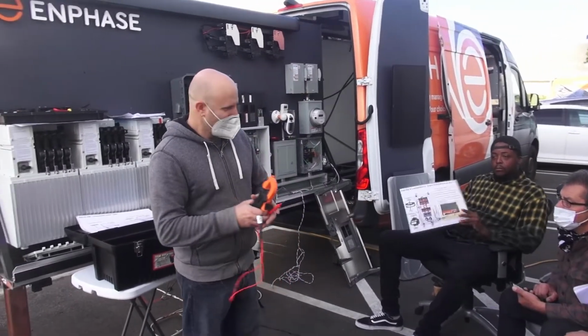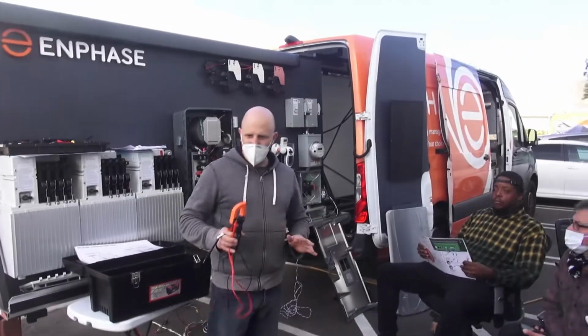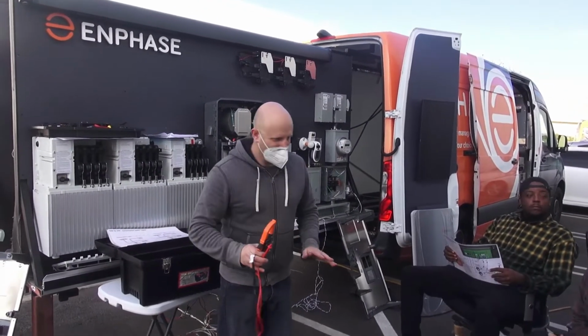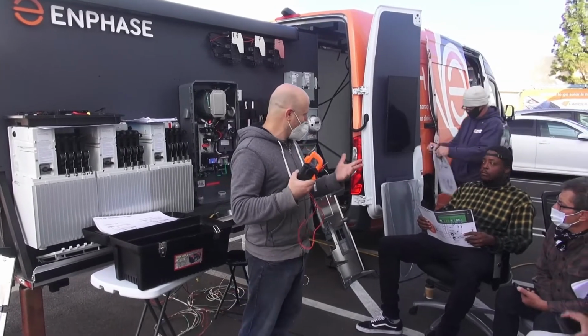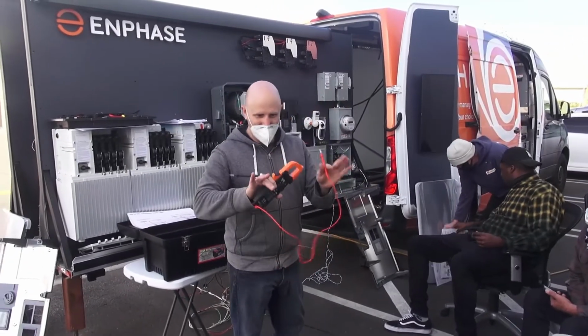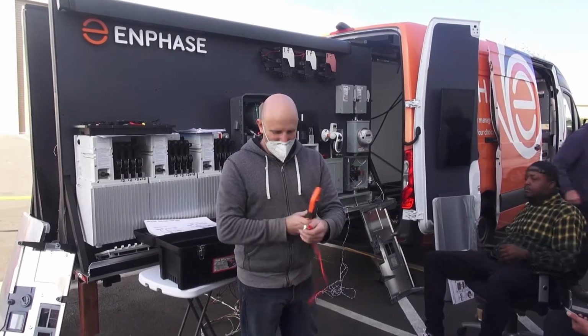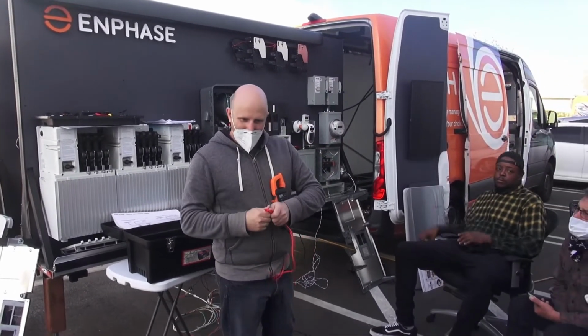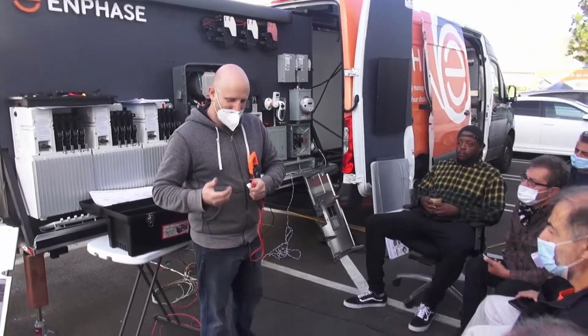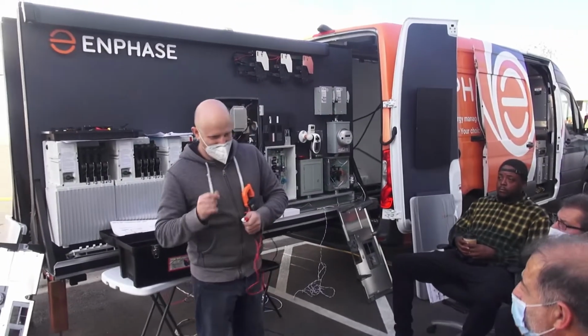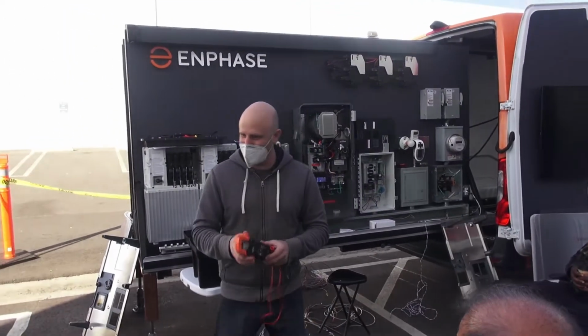You can reuse it. And the point is, yes, this takes a couple minutes, but this saves you from driving back, hours, right? It's worth it. So it's easy to make this longer. Literally just a wire knot. I usually say use a number 14 or 12. Zip tie it so that this doesn't keep popping out and making you crazy. I promise you, this is how you're going to troubleshoot some sites.